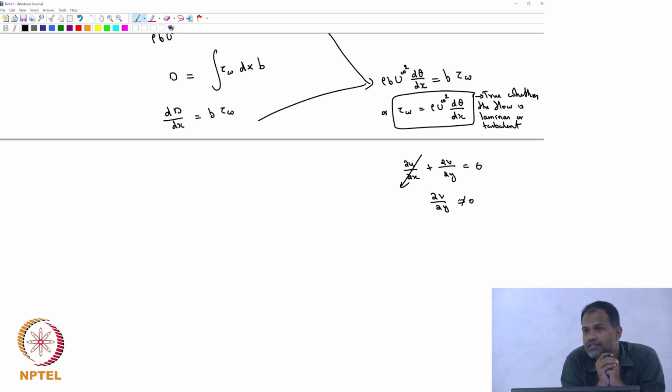We know that mass conservation is true whichever case you do, whether it is laminar, turbulent, whether you talk about average or fluctuations and so on. So it will be true in general. The v velocity develops because the mass has to be conserved. It must have a better explanation in terms of the total flow rate, but I can't think of anything as such.